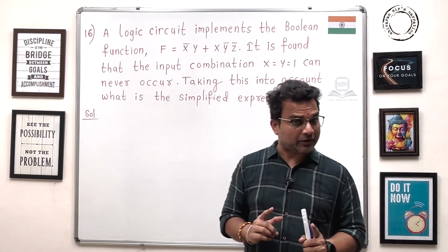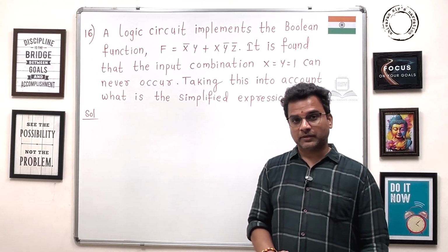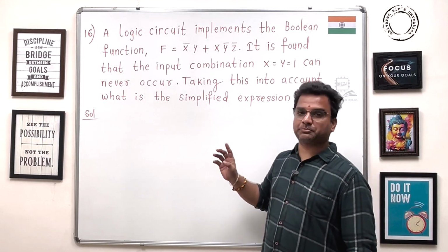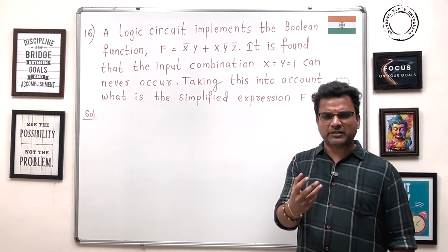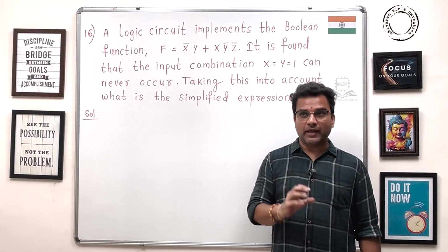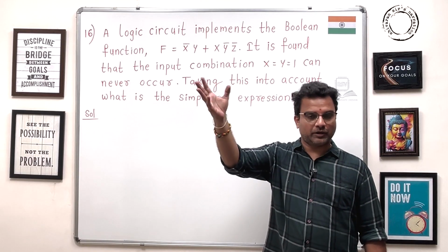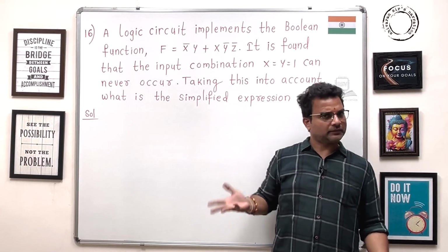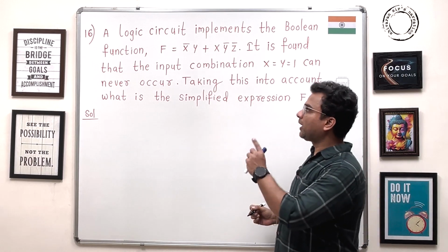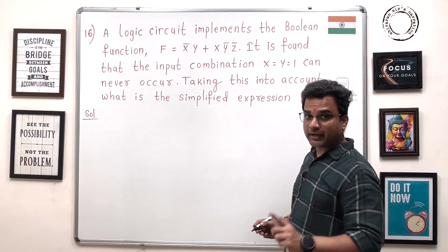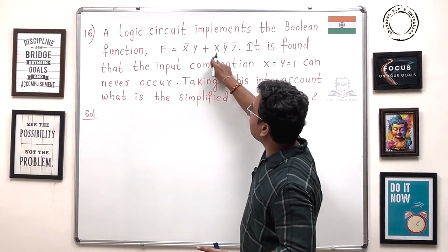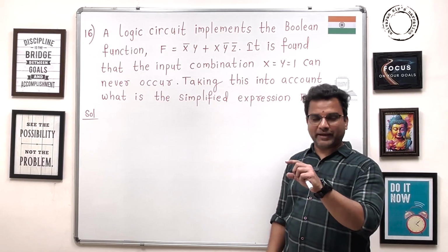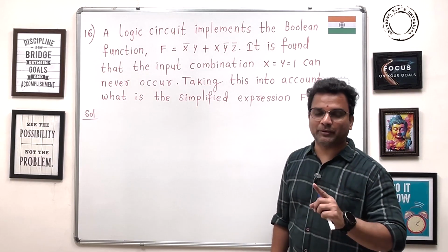So as per the design requirement, you need to get the expression and then simplify using the K-map. That will be the simplified expression. So it is always a two-step procedure. Step 1, you need to get the truth table and map it to the K-map. Step 2, simplify it. Okay, now let's consider the f value. Guys, it is in simplified form, but if you want to write it in truth table format, it might need to be in standard SOP only.